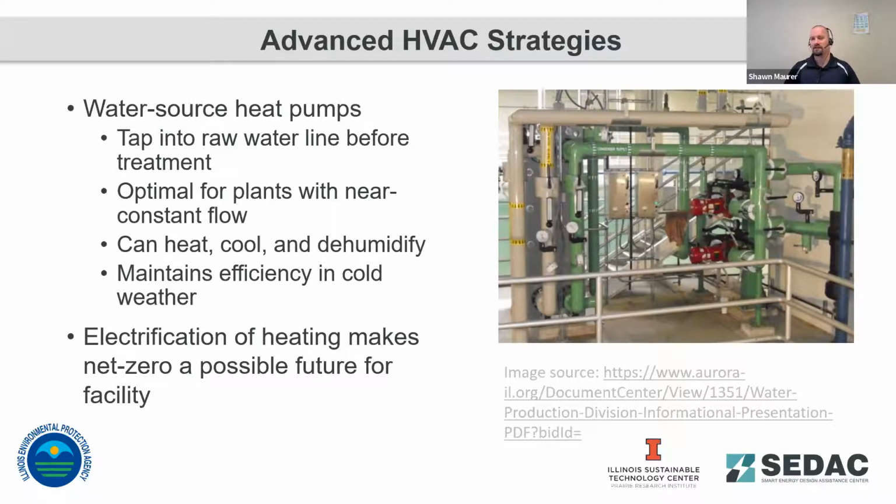somewhere between, for older systems, about 75% efficiency. For newer systems that are standard efficiency, about 80-85% efficiency. And then if you've got condensing systems, you're at 90% efficiency. If you can put a heat pump on there, it's somewhere between 250-300% efficiency on the electric side.